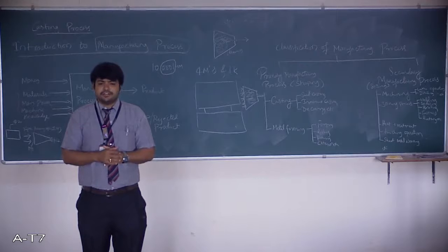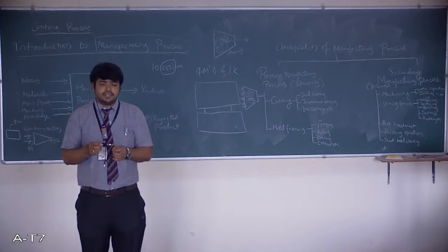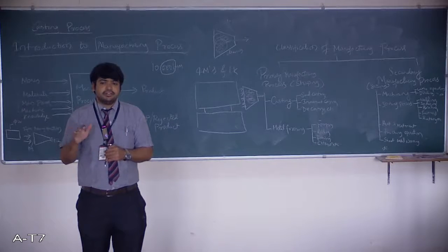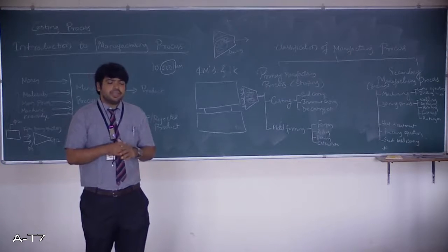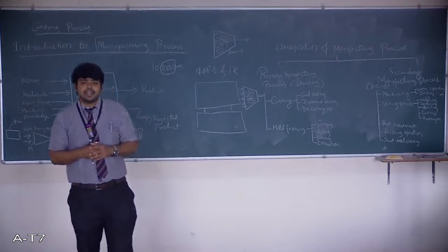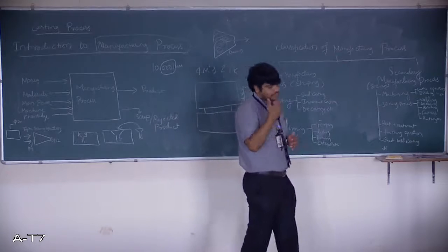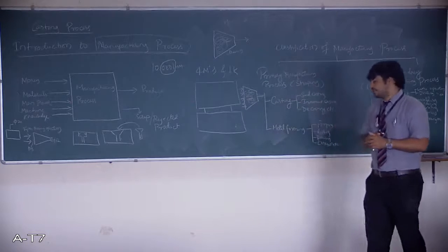There are again different techniques like normalizing, annealing, and quenching. If we heat the metal to its recrystallization temperature, allow it to settle there for a certain time, and then immediately cool it in water or oil, we term it quenching. By such processes there will be a change in the mechanical properties, and those are done by this heat treatment process. There is also something called the case hardening process. Like that, different types of heat treatment processes are there.